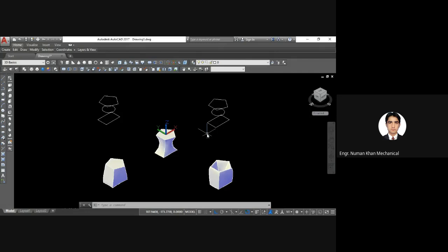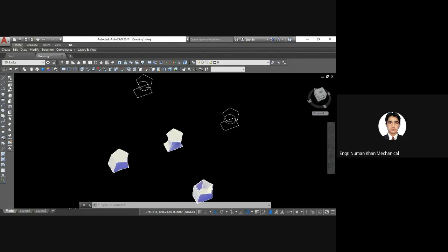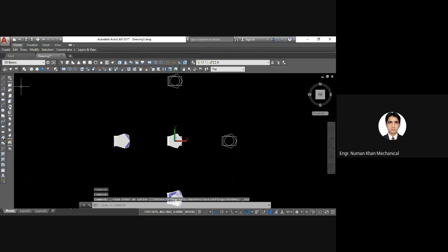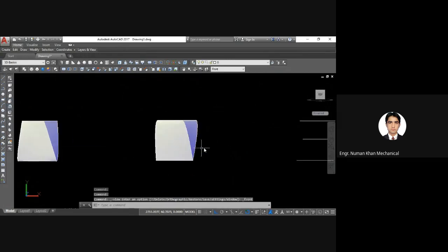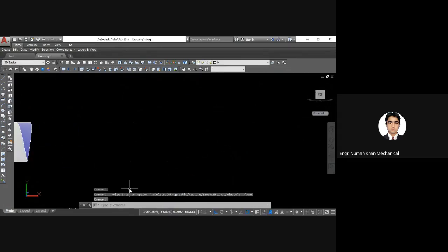We can also use a path option over here as well. For that, let's say we have drawn all these objects in the top view, so I will select the side view to draw a path over here, just like the extrusion along a path. And let me select a spline. Normally it uses a spline for the path.